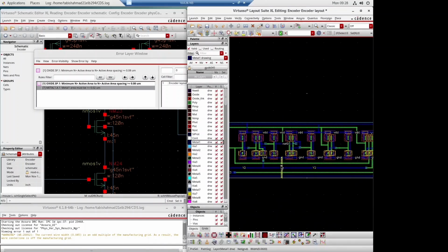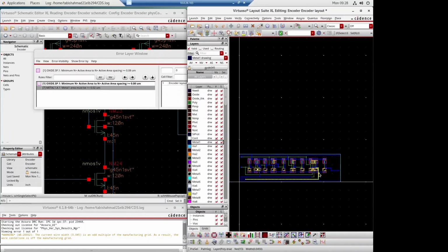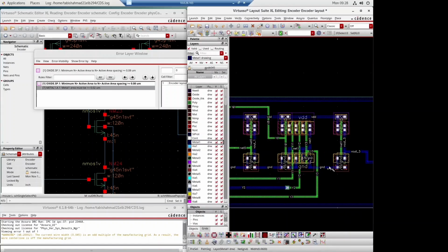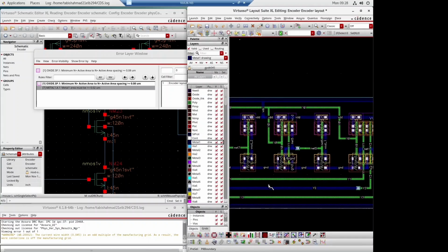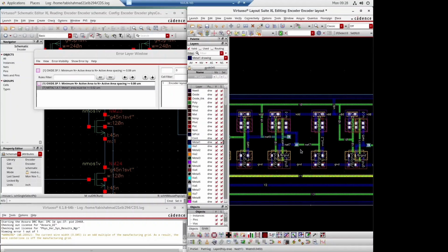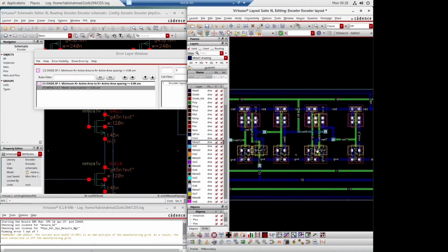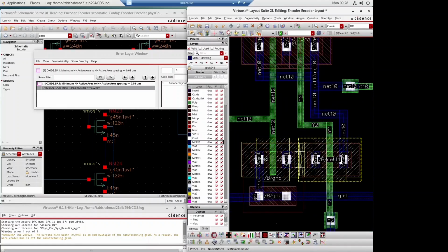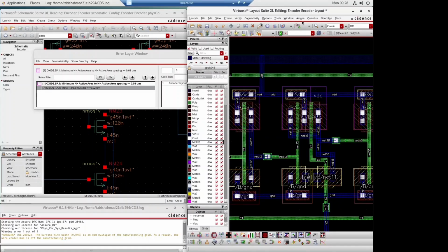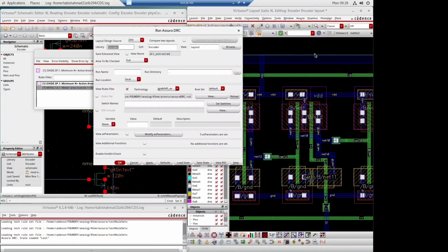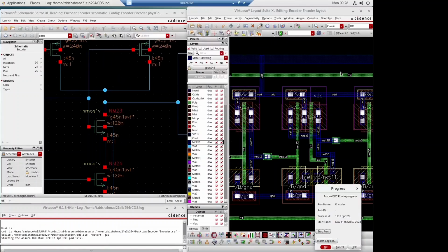You can see this metal line is intersecting with the Y2, so they will be interconnected. So what we will do now is, instead of placing it there, we will place the ground connection with the ground, this one here. Now they will not intersect. Okay, coming back to our problem. I hope there will be no errors now. We'll remove this old connection, make a new connection, and again run DRC. Okay, enter. Okay.